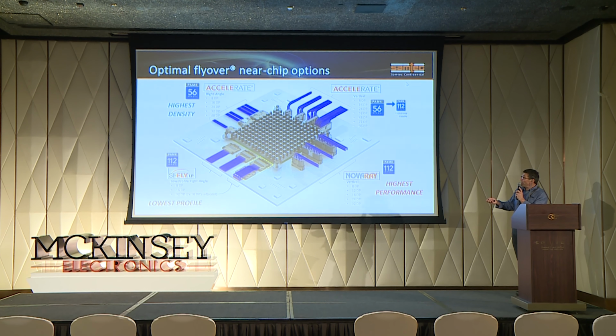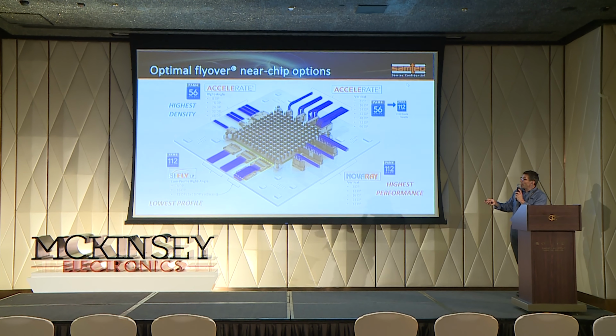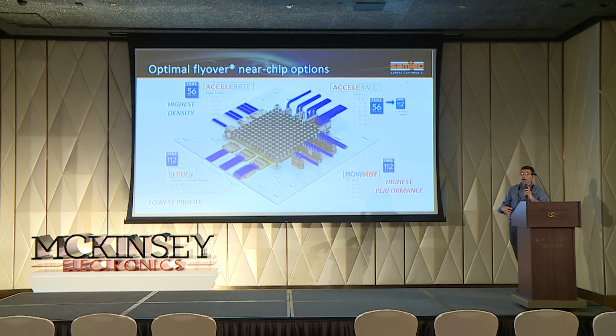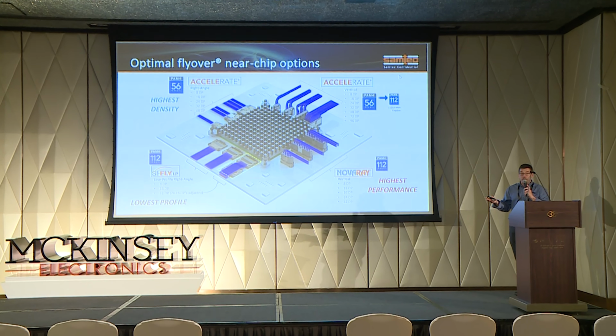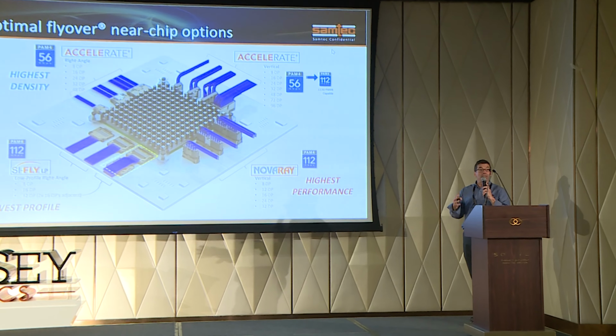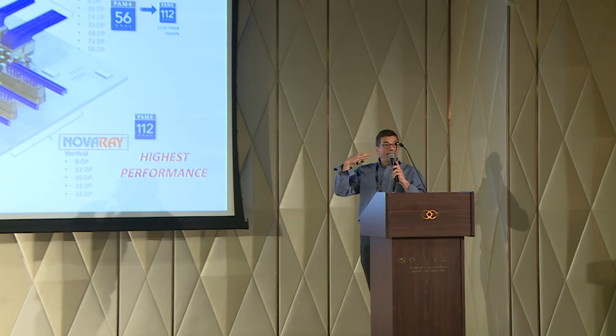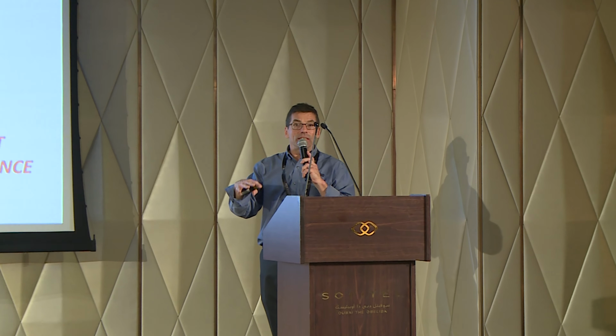So in the case of the Accelerate series here, this is what we call sort of small, fast, and cheap, because it's quite a miniature package. It's available as vertical, right angle, 8, 16, 24 pairs. It's great for 56 gig PAM4. So when you're looking at OIF, CEI, VSR 56G as a standard through the IEEE bodies, then we can build a system based on like an ARC6 to a QSFP front panel, look at the losses by the standard, and we can do some simulation work and demonstrate compliance.